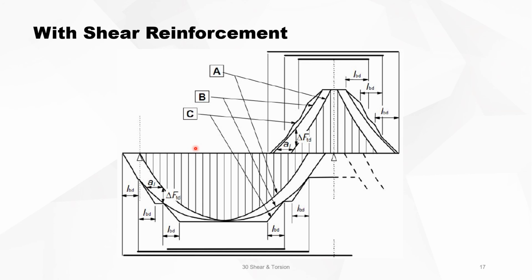The shifting of the bending moment line can be easily explained. Suppose this is the original bending moment. In the middle here, you cut it and you shift it over the desired distance, and you arrive at this bending moment line. And because this line is shifted, it mimics the effect that you increased the tension in the tension reinforcement. You see that the delta FT is 0 when the bending moment is maximum, and is maximum when the bending moment is 0.